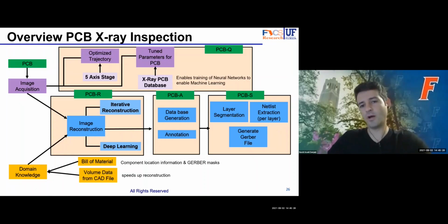So if I do my optical inspection and I know what part of the board is dense and what part of it is sparse, I can use that information and give it to my X-ray tool, and then save time, and also give some prior knowledge on how to collect the X-ray images from the dense domain and how to collect them from the sparse. So eventually we have the minimum noise or attenuation from the high Z images.